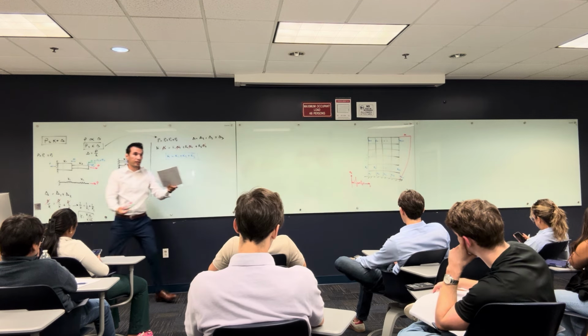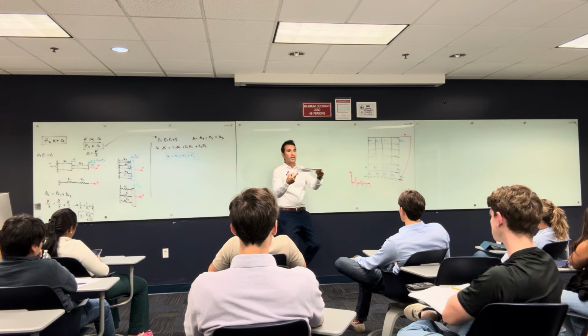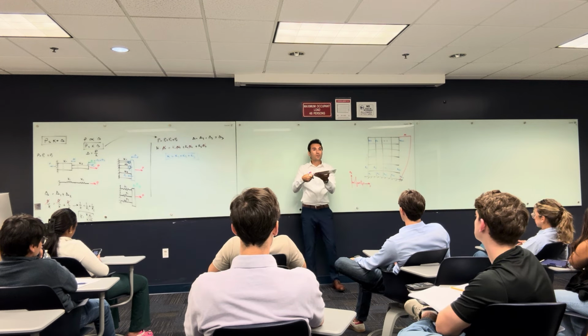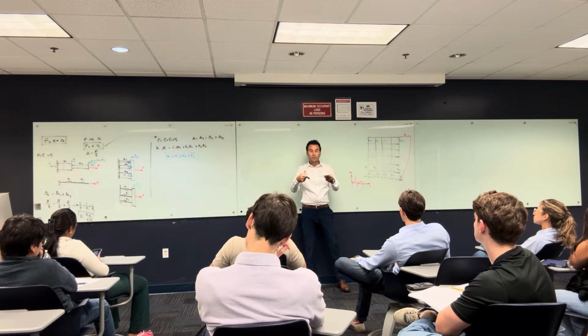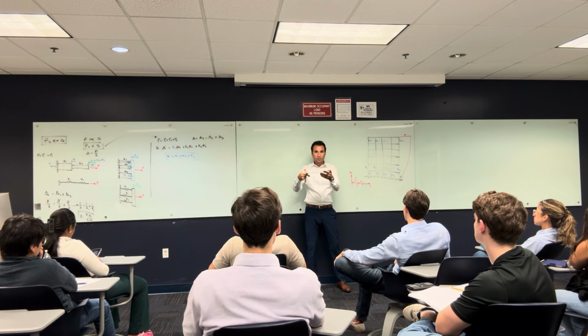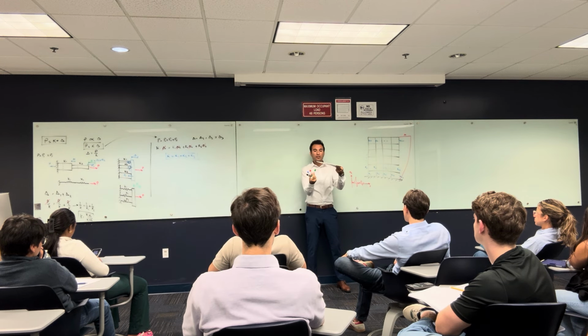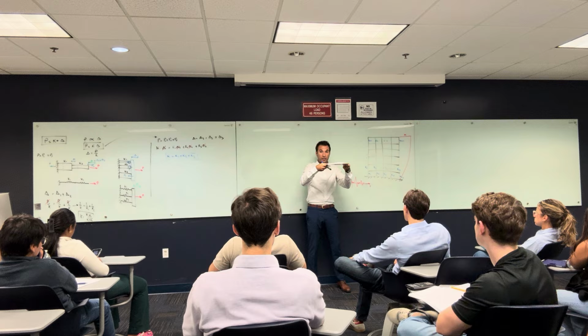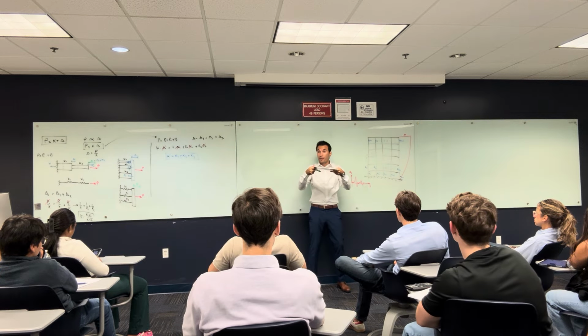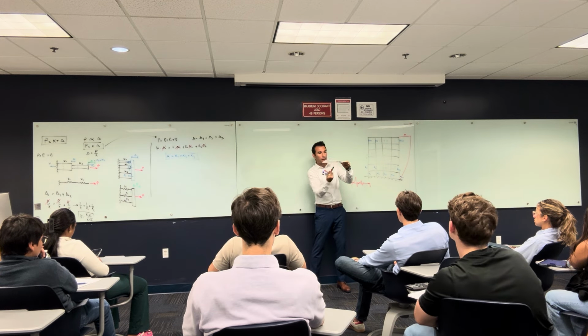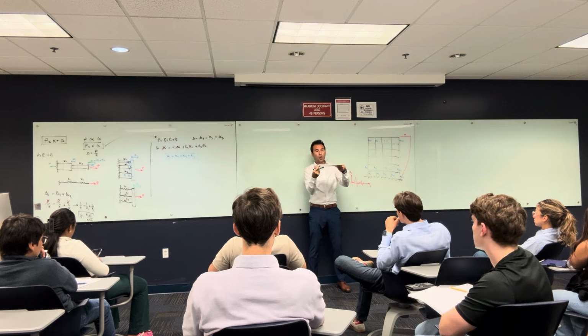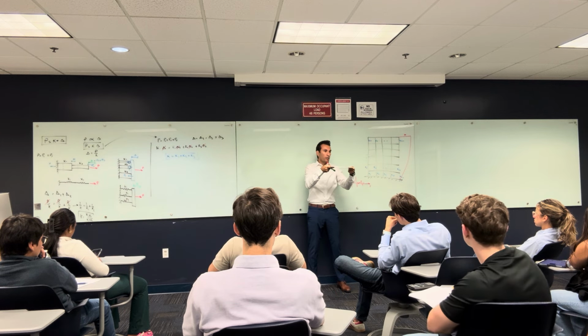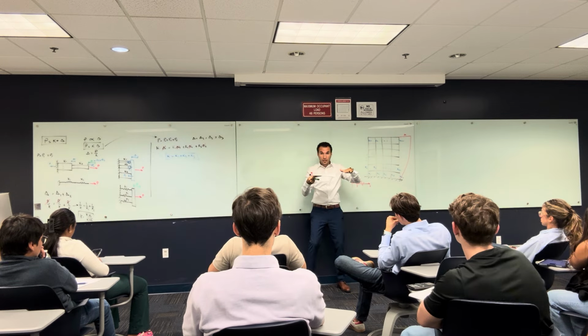Let's assume this is the slab system, and there are columns here. We call it a rigid diaphragm, meaning this slab system is very, very rigid. If it moves that way, all the columns have to move that way with it. If you have a column here, a column here, a column there, all the columns have to make the same deformation as the slab system. Are we on the same page with that?